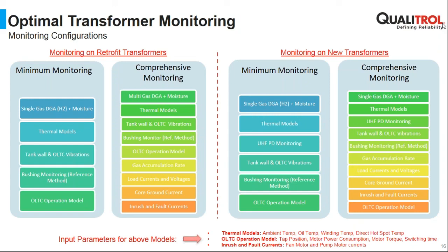Okay. How can you check that the transformer radiators are working properly? Yeah, the radiators, you basically look at the power consumption of the motors of the radiators.